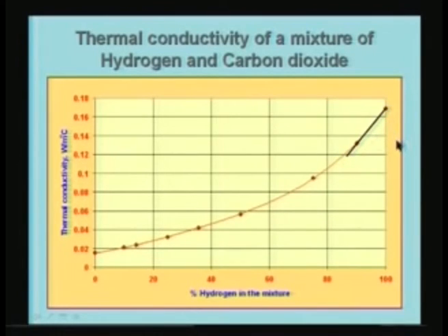That means that the thermal conductivity change between the carrier gas and the carrier gas plus CO2, which I was talking about earlier, is a small amount, and in that range I can use a linear relationship between the thermal conductivity and the percentage of CO2 in the mixture, because 100% hydrogen here means, 80% here means 80% hydrogen or 20% carbon dioxide. So, in other words, I can say that 100 minus whatever value gives you the percentage of CO2 here. Okay. If it is 95%, that means 5% CO2. So, the thermal conductivity comes down very slightly.